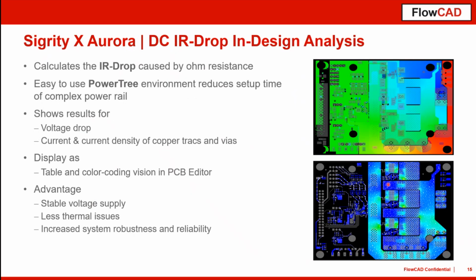So let's start here with a DC analysis, meaning the DC IR drop analysis. To do this, we need to define the VRM, the voltage regulator, as the source, and the sinks, where we need to know how much current goes into the sinks. That's all for the setup.